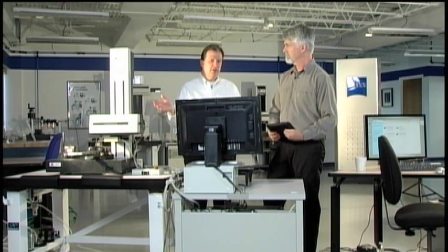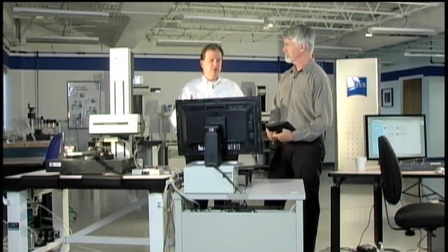So tell us about the Surfcom, right? The Surfcom 2000 is the instrument we're going to use to demonstrate the software. One of the reasons is that it has a long-range probe. The long-range probe allows us to measure surfaces with a lot of shape in them, where a traditional surface roughness instrument may have too short a range and not be able to measure over those larger features. So that gives us the ability in the software to do both surface roughness and contour.